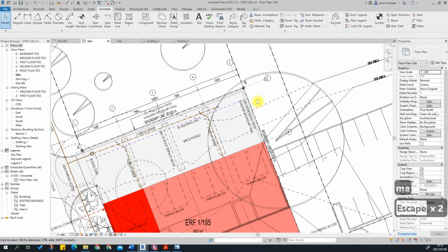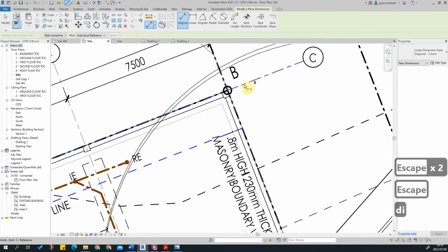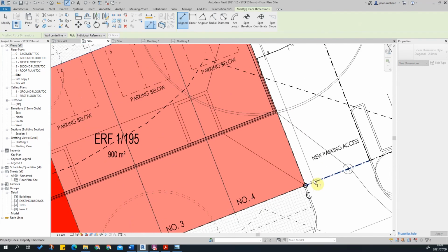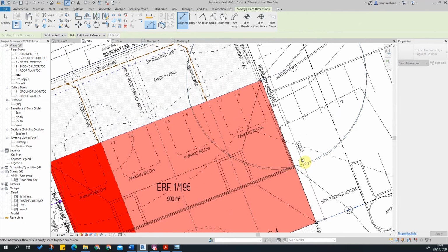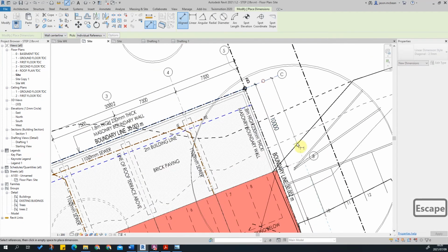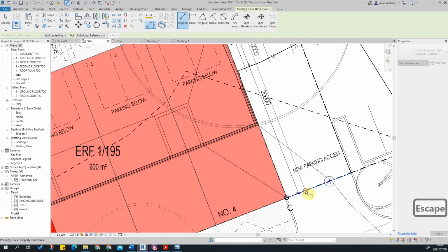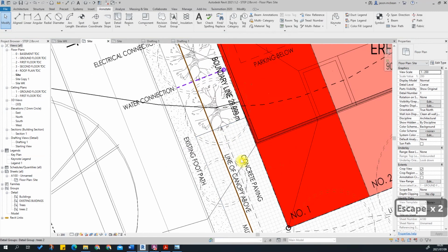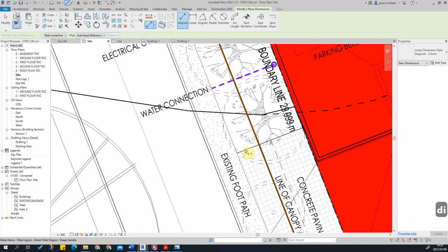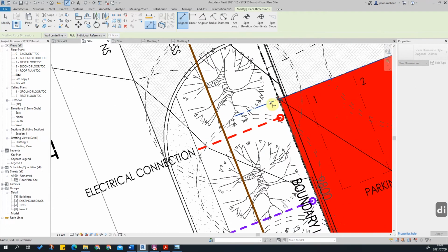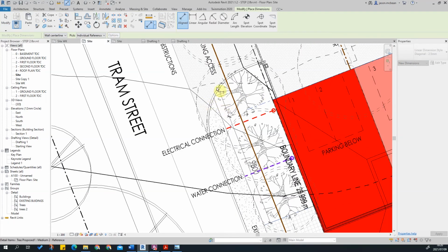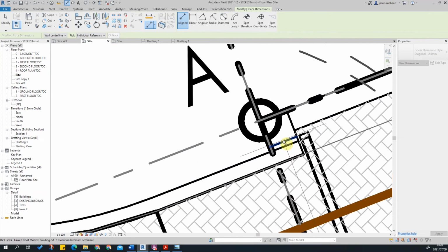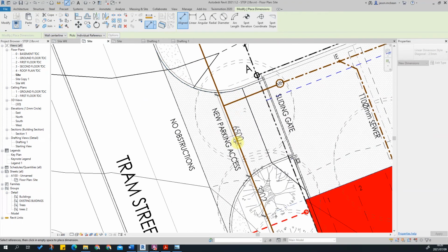Now we've got some different dimensioning to do along here. From there to there, and then from there to the front of our building, again, overall. Where things change, we might need to denote how that works. So maybe a dimension along here, from there to there, and where this opening occurs, from there to there. That's the opening in that brick wall.